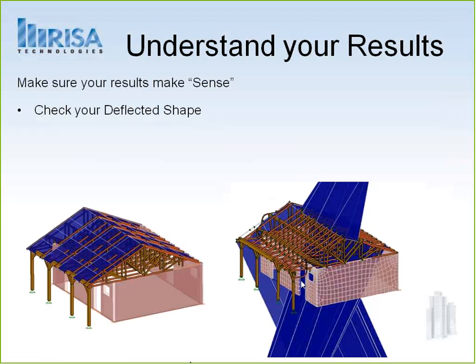Okay, so those members, and this is just 40% magnified, so it's not really that much magnification. All we're really seeing is things are not properly attached on this model. The plate members are not physically attached, and as they're not physically attached properly, they're just flying off and causing havoc in the model. Okay, so the deflected shape is really the first spot that I always make sure, hey, does that deflect the way I thought it should?